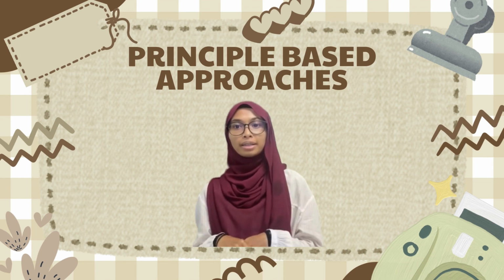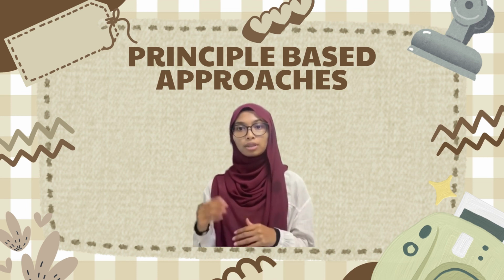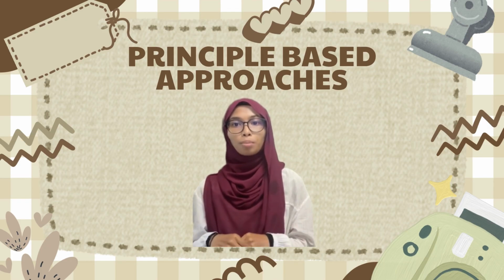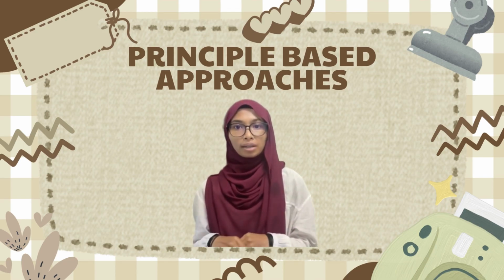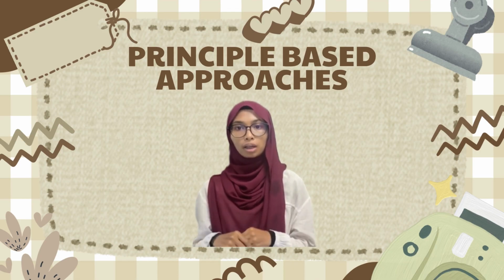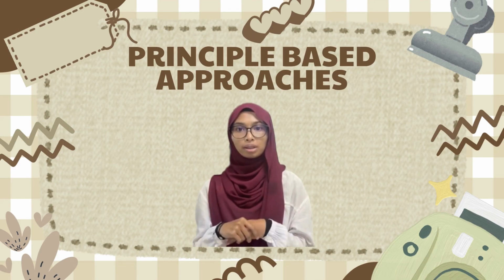The inverting amplifier is clipping because the theory showed the output of negative 33 volt was too big for the 15 volt power supply. Thus, the op-amp already hit the limit. The non-inverting ideal output shows 11 volt, which is well below the 15 volt supply limit. The op-amp stays in its linear region. There is no saturation or clipping issue, unlike the inverting amplifier.